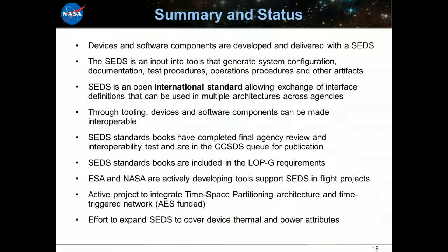If you had a device like a reaction wheel that talked over an I2C bus, would the EDS include I2C commands to talk to that device? It doesn't. Take SpaceWire as an example. It doesn't say how SpaceWire works or how 1553 works, but it does use the language of 1553: whatever the data units are, they come over through these subaddresses.